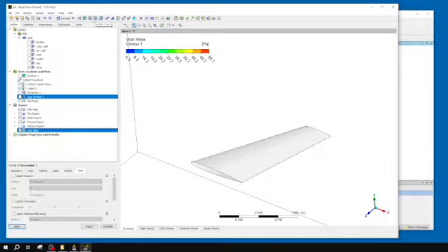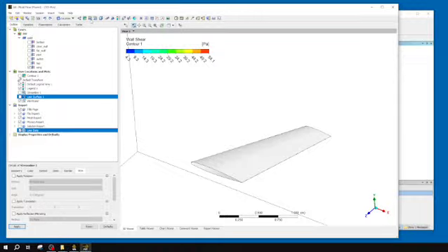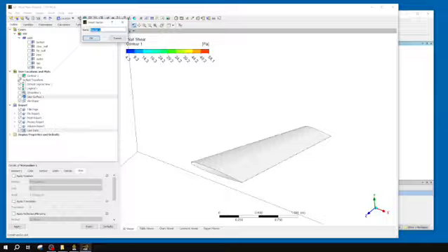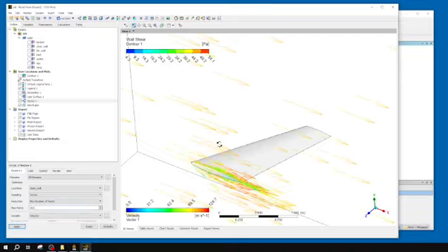You also have particle tracks, which I'm not going to go through entirely. They're very similar to streamlines, just a tad different. They're basically solved slightly different. That's the main thing with them. You can make a vector plane. I'll make a quick one for you, just so you can see it. I'm going to put it on my close wall here. Reduction factor, I like max number of points. Let's go 300 maybe? Let's see what that looks like. Yeah, that's not bad.